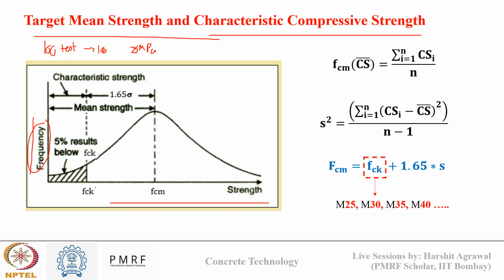Okay, so when a mixture design is done, different concrete assemblies are prepared, like cubes and cylinders. Now, not all assemblies will have the exact same strength. When I'm pouring concrete into molds, in some cases there will be lesser paste or more aggregates, or the void percent can vary from one cube to another, or maybe two mixtures are prepared with the exact same proportion, but they can still vary in their properties by a bit.